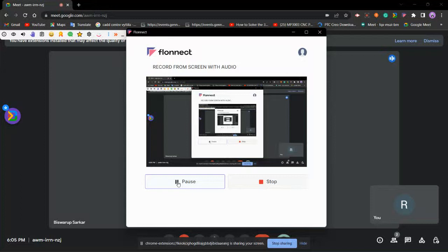And there is an option called mirror extent. If I'm giving mirror extent, 125 will be applied in the opposite direction, so 250 will be the total dimension. It is not similar to our mid plane. In mid plane, the entire length is divided into two, but here it is doubled. That's the only difference between mid plane and mirror extent. If there is no mirror extent, it will be like this.